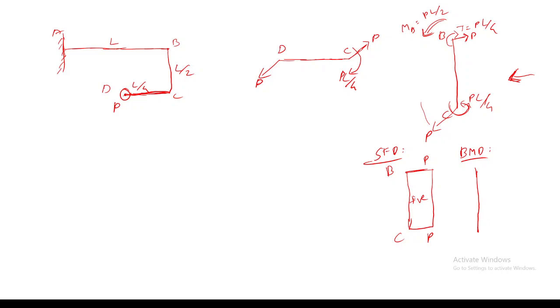And which surface actually gets contracted or elongated? Or maybe you can see in which plane it is actually acting. For example, in the right side plane, I'm having this member BC, and I'm having this loading, bending moment like this. This is actually P. Is member BC positive?